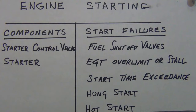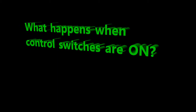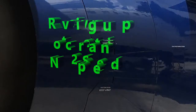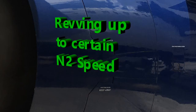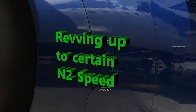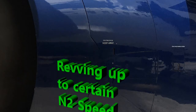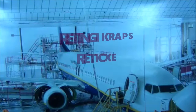Generally, we're talking about a sequence that occurs when the engine master control switches are switched to on, and then that starts the process with starting. The concept here is to have the starter essentially boost and turn the engine to get it going up to a certain N2 speed, and after that it's not necessary to have that starter on unless there's a necessary application in flight for it to be restarted by the pilot.